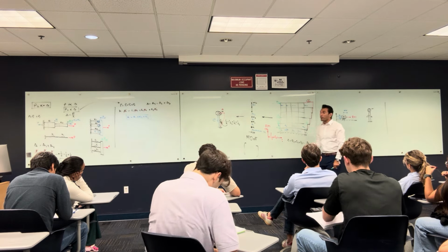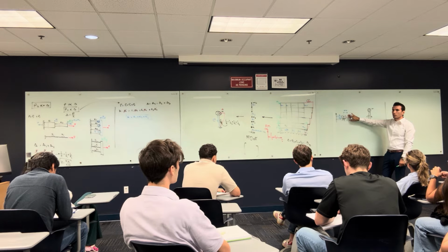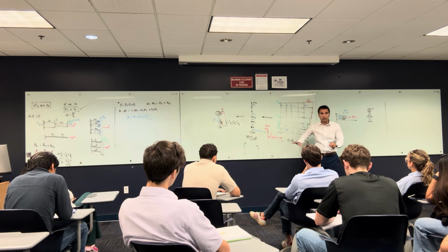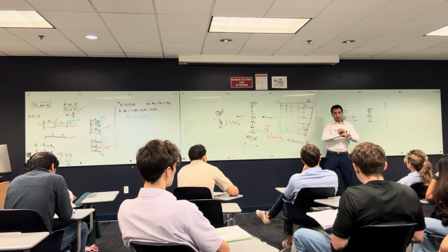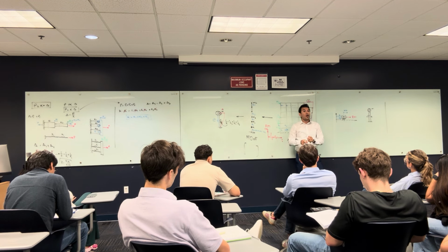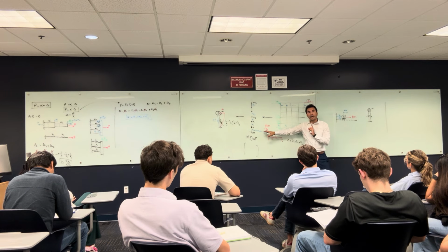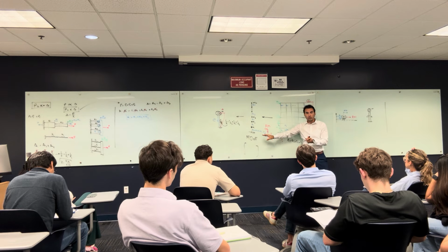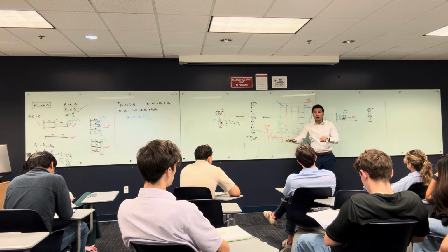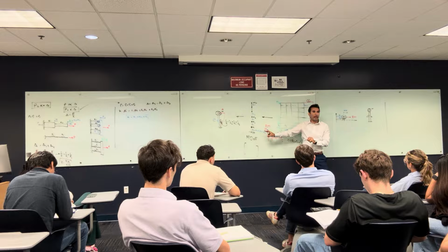MA. By the way, I want you to focus. MA is the inertial force on the structure. AG is the acceleration of the earthquake. Let's say you have, I don't want to say Miami because earthquakes don't happen here, but let's say Los Angeles. Los Angeles is going to be exposed to an earthquake. When we say an earthquake, what is the AG of the earthquake? What is the ground motion? What is the ground acceleration of this earthquake? It's one ground acceleration for an entire zone. So all the buildings are going to be exposed to the same AG, the same ground acceleration.